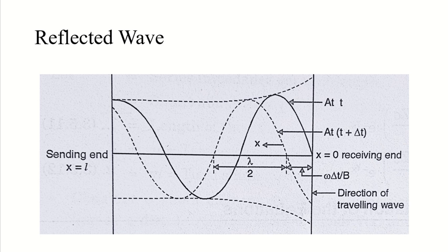Now quickly coming to the proximity effect. What happens in the proximity effect is that the flux of two conductors, let's say I have two conductors A and B. When the first conductor, A, carries my AC current, the flux of that conductor will link with the other conductor B, and the half portion of conductor B which is facing conductor A will have more flux linking than the other portion, right? And this effect is called proximity effect.